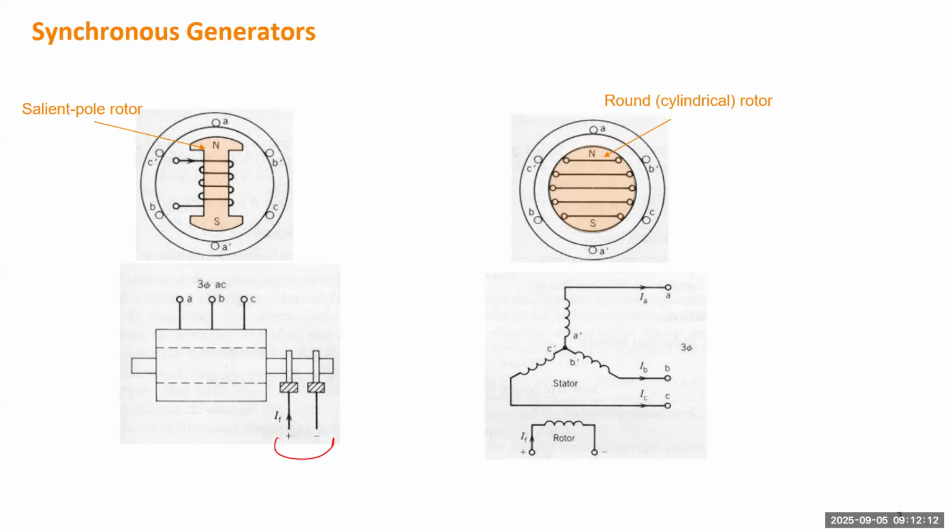which is called the exciter. When you take a 422 course, it will cover more about the modeling of the excitation control that influences this field current to make the magnetic field stronger or weaker. When the rotor is revolving, usually we consider the counterclockwise direction to be the positive direction. The magnetic field will have flux cutting the armature windings, winding A, winding B, and winding C. So there will be current and voltage induced in each winding, to power the external system.